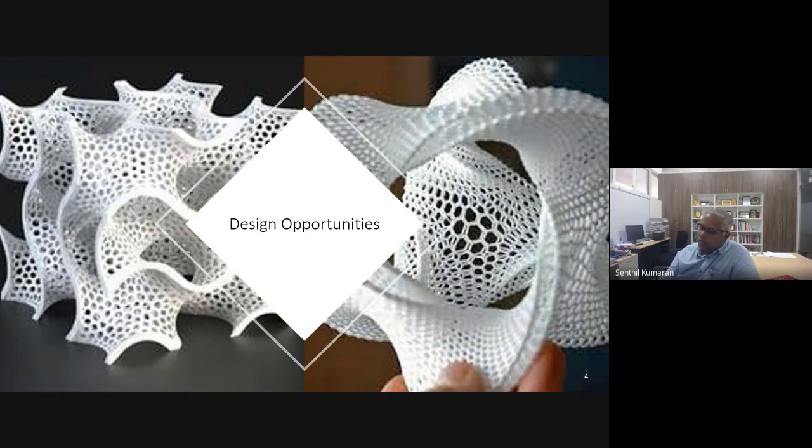They found titanium to have some issues. Titanium has a stress shielding issue, which I already explained. The bone needs stimulus to grow, right? Whatever forces you give, the bones degrade constantly. Every year you are replacing your bone cells because they degrade constantly, and then new bone cells form. As you bite more, new cells grow, right? So when you put in titanium, the stress that the bone receives is shielded by the titanium implant.